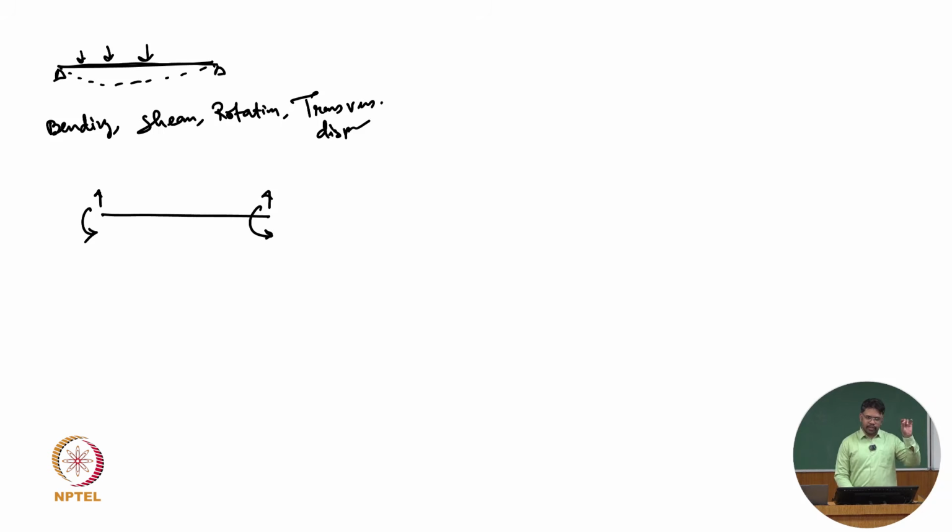So in each node of the beam we can see two degrees of freedom. One is transverse displacement, maybe we can write it W, and rotation theta. These are the two displacements we can see, transverse displacement and rotation. In case of the bar, what was happening? Axial deformation was the degree of freedom. Now here, these are the two degrees of freedom we can see.